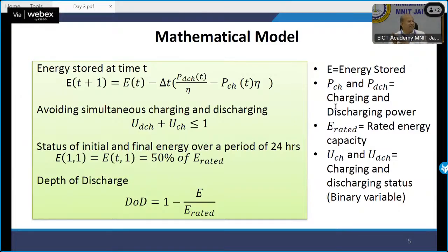to come to a zero state. So to avoid that, we also ensure that the state of the battery over a complete 24-hour cycle must be the same. If it is fully charged, it must be left fully charged. If it is 50% charged, it must be left with 50%. If it is zero charge, it will be left with 0. So the state at which we started, the battery must end with the same state, okay?